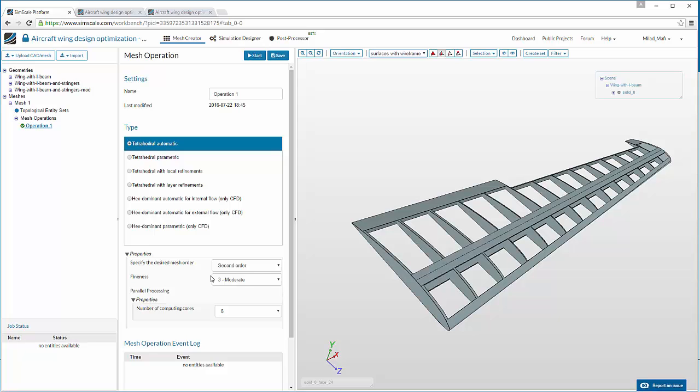And there are a lot of reasons for using or avoiding second order meshes. First of all, creating a second order mesh needs more time, so more computational time, is more complex and has a higher chance to fail because of problems with the CAD model. On the other hand, you will have a better approximation later on of the equations we use, so you will have better results, and it also can sometimes make it easier to solve complex geometries.